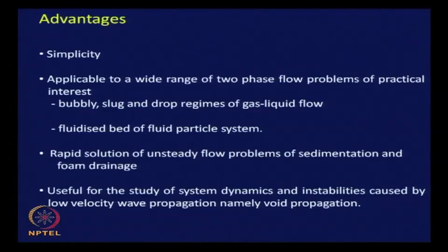First thing is definitely simplicity, it goes without saying, it is much more simple as compared to the two fluid model. Secondly, it is applicable to a wide range of two phase flow problems of practical interest. Now, remember one thing, for example, the slug flow pattern: can you call it a completely separated flow pattern, or can you call it a totally mixed flow pattern? If you think it logically, it is neither, isn't it?